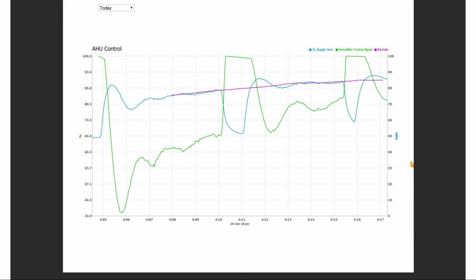And if we looked at the temperature graph, it would be like a seesaw or maybe a sine wave where the temperature goes up, hits the set point, the heater turns off, the temperature starts to drop, it'll go to a certain level, the heater will come back on, and you end up with this constant cat and mouse of the temperature going up and down above a set point, but never actually maintaining the set point continually.